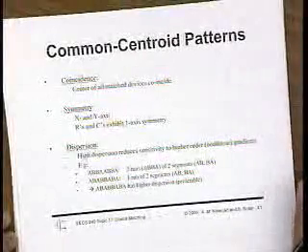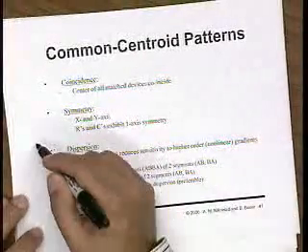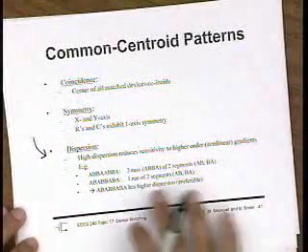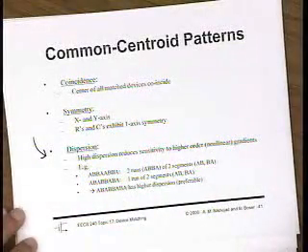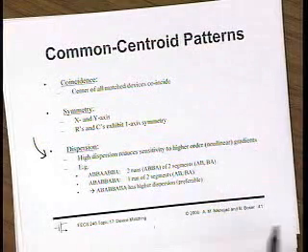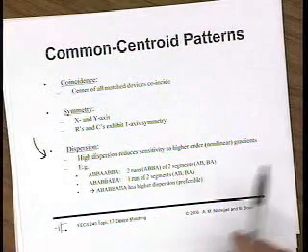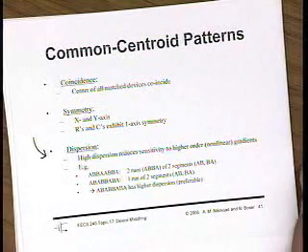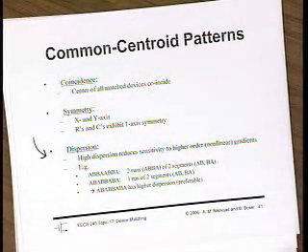And this is kind of a repetition; we talked about it already. One thing we didn't talk about was this concept of dispersion. So lay out your device in such a way that it has what's called here high dispersion. I like to think of it more as intermingling. Take your devices and make sure they're as intermingled as possible.